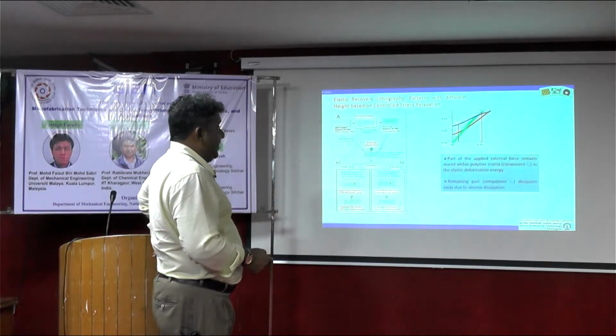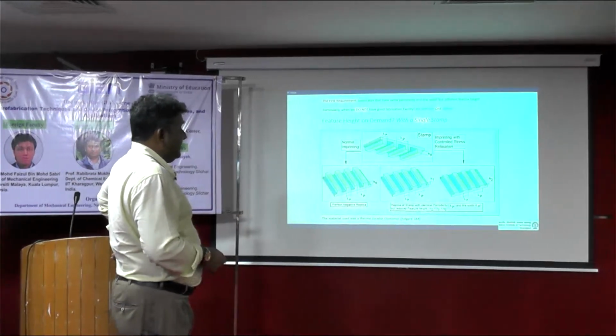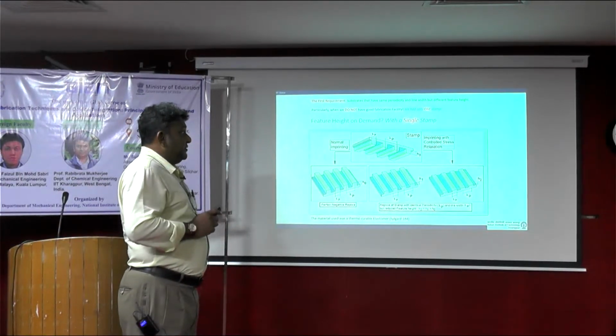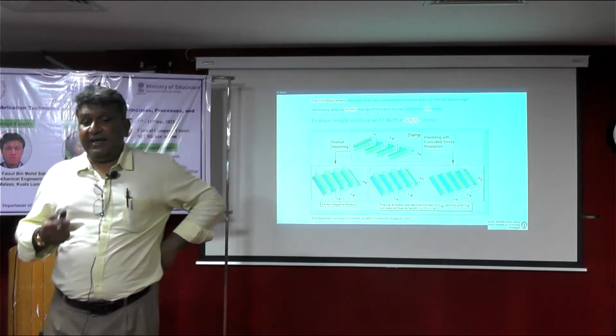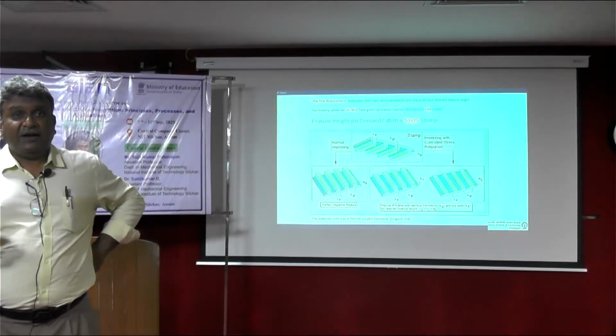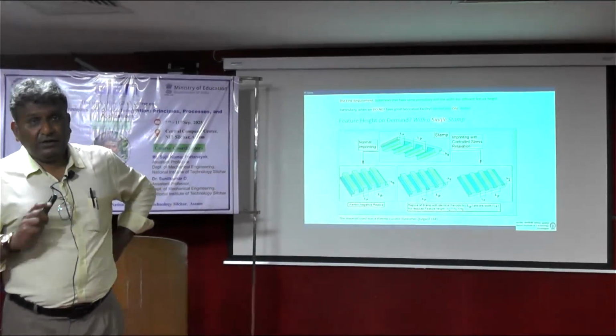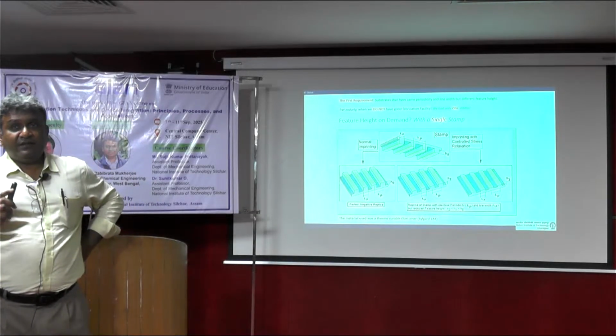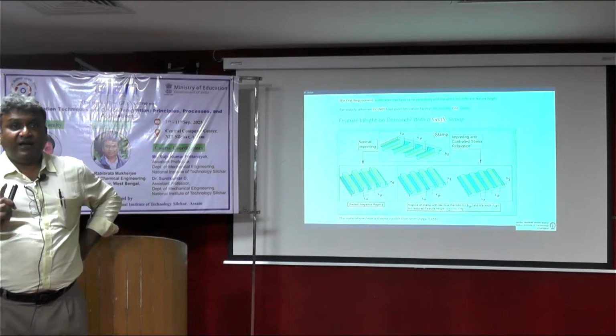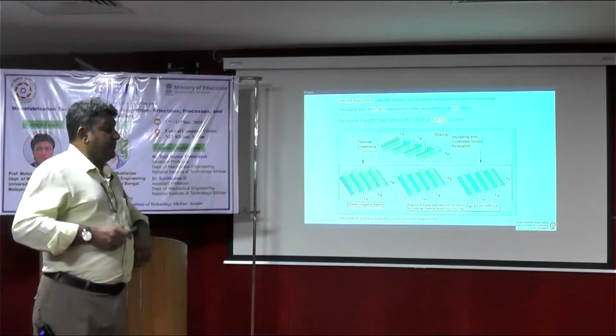So in a nutshell, we actually could achieve creating patterns which have the same line width but different feature height using a single stamp by cleverly utilizing the concept of viscoelasticity and stress relaxation.